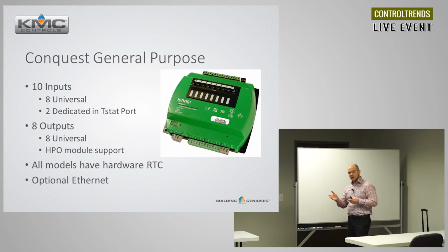A lot of our reps like estimating jobs of those because they can count up their outputs. They apply whatever their takeoff amount is for that, $15, $20, whatever they're going to charge. They don't have to worry about picking a controller with the right mix of HOAs, triacs, relays, etc. So it's really universal in a software sense as it's programmable, and it's universal in a hardware sense because you can make it so many different things but still have an integrated controller in the end.